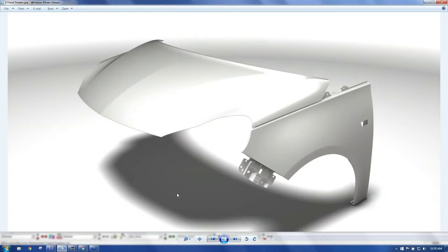So what I did here was just shot a couple of images of the way that I use my workflow, whether it be going into any one of the various tool sets for visualization. What this shows is just my hood and my fender export. This is after I've already exported out my complete car. So I verified that, yep, the parts are coming in the correct position. I've verified that the coordinate system is correct, even though obviously it's shown on the floor here.